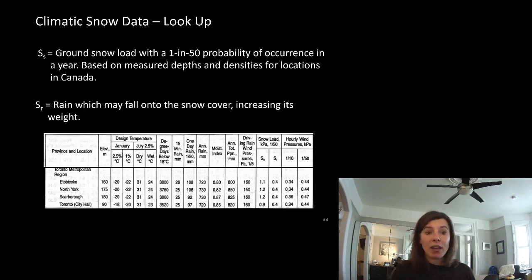Now, I don't know how many of you live locally to here, but I think it was 2013 where we had a massive rain system park over specifically Etobicoke and the western side of Toronto. And in an hour, they got 127 millimeters of rain. So far exceeded the 1 in 50 year 24-hour rainfall event in 1 hour.